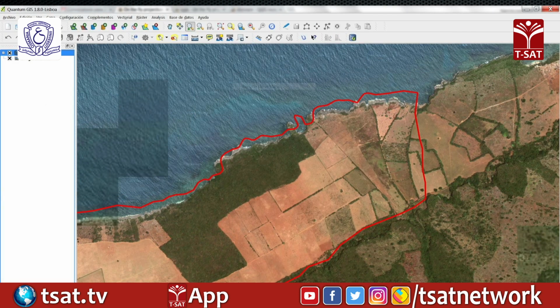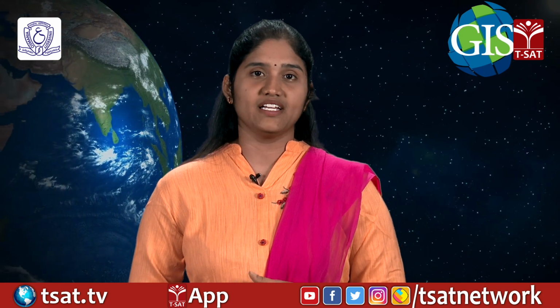If a data set has an unknown coordinate system, the GIS package may use an assumed coordinate system. On-the-fly projection does not actually change the coordinate system of the data set. Thus, it cannot replace the task of projecting and reprojecting data sets in a GIS project.